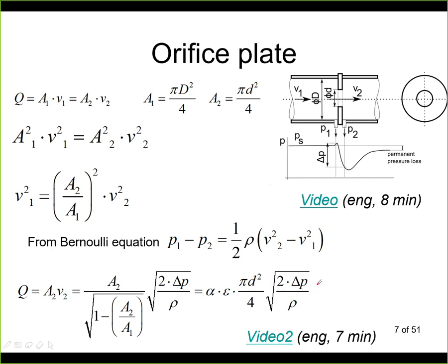So we take a pressure gauge, we measure a differential pressure, and we calculate this flow. Now note that this is a square root dependence, so it is typically linearized with some electronic circuit. The basic dependence is non-linear. We can see it here. It's a square root dependence.